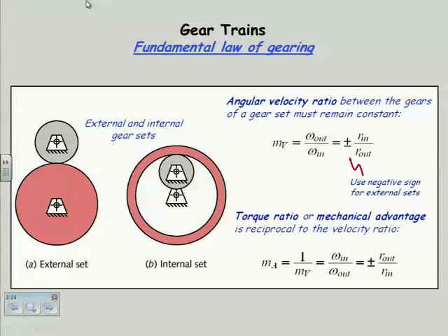And as you know, the purpose of a gear set is to trade speed for torque or vice versa, the product of those two things being a constant for a given amount of power in the system, because torque times speed is power. So if I increase the speed, I have to reduce the torque and vice versa. So the most common application for gear sets is to reduce speed and increase torque, as in the transmission in your automobile, where you want to get a lot more torque to start the car moving, put it in a gear ratio that has an increase in torque, and you trade off the speed.